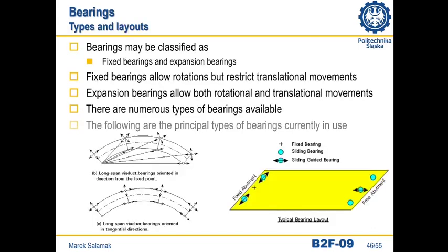We divide bearings into fixed and sliding ones. Fixed bearings, despite their name, block horizontal movement but allow rotation in all planes, especially rotation resulting from bending of the span. Such restrictions are no longer imposed by sliding bearings, although we can receive movements in a specific direction. The bearing arrangement is of great importance in long bridges or with a large angle or curvature in the plan.